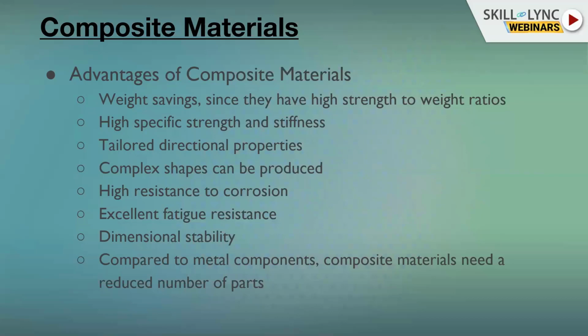And this is one of the most important points where composites have an advantage over conventional metal assemblies. When you have a big part like an aircraft where you're connecting a lot of parts, you need metal parts to be bolted to each other, riveted to each other. A lot of fixing and accessories are required. Whereas in composites, they are either bonded or laminated together, which is called co-curing. So you can eliminate the use of doubler plates, fixations, fasteners and rivets.